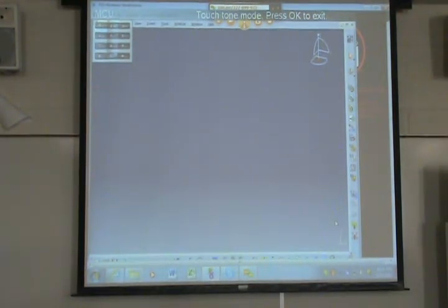First thing we want to do is create a skeleton. A skeleton is just a wireframe using basic geometry to represent the relationships of your parts. Okay? So we talked when I gave lecture about top-down. I know I kind of cruised through it really quickly, but there's two things that you want to do when you're creating a top-down. The first one is you want to identify key system level relationships, and the second one is you want to identify key system parameters. Okay? So we'll start with the relationships first.